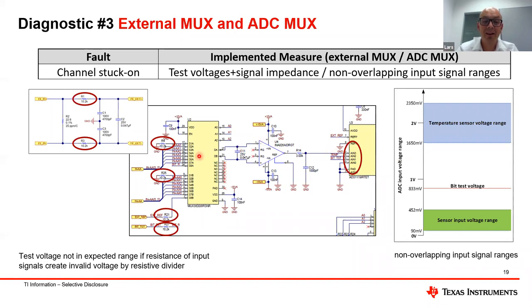In the unlikely case that here is a 0 voltage, it could be because of the common mode voltage, right? It could still be that this one can be 0 or this can be 0. Then we would figure that out by sensing the second test voltage, which is S8. This is actually a 0.4 volt test voltage here. And this would actually not be measurable if there would be one channel stuck to ground, for example, here. You could also figure that out in all cases.